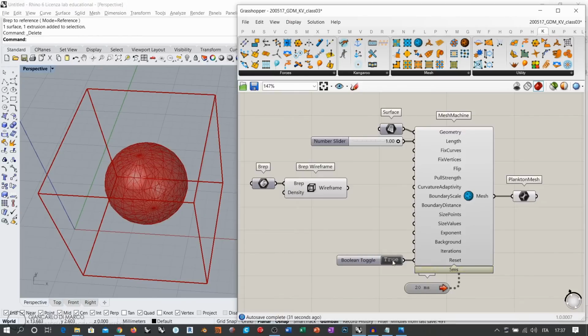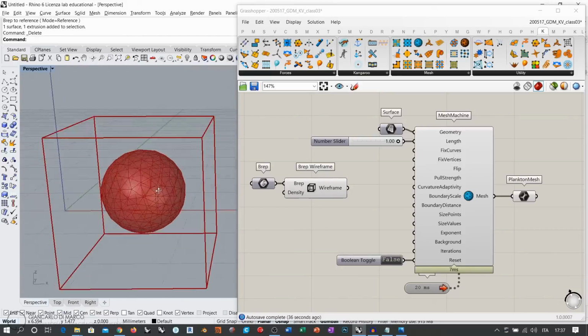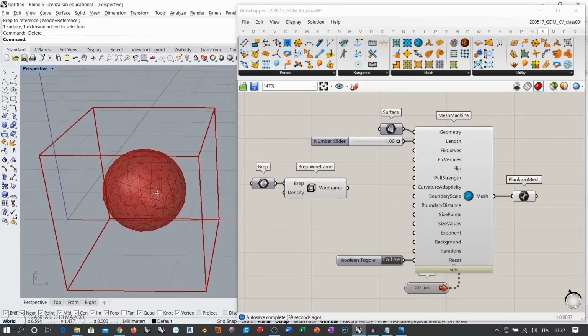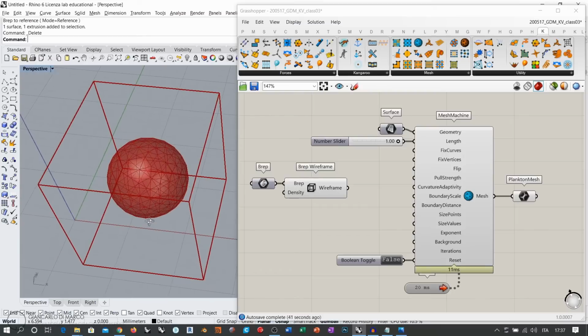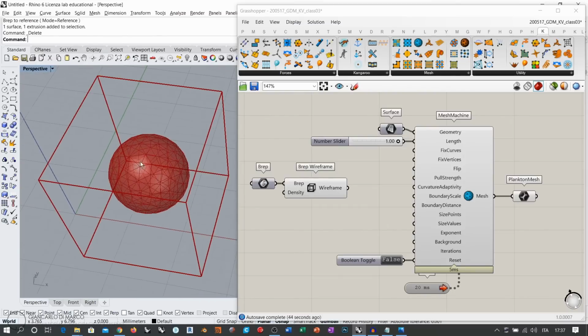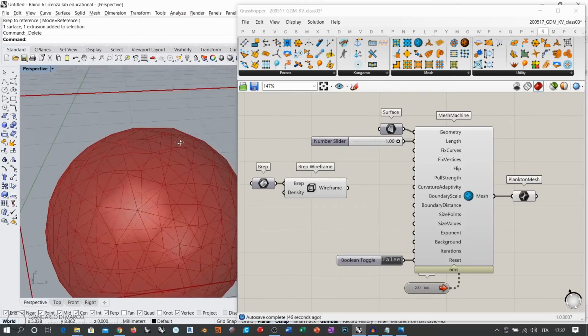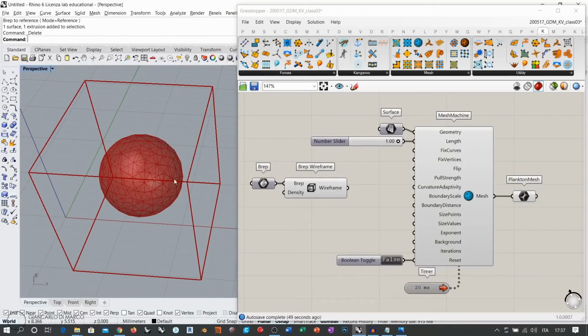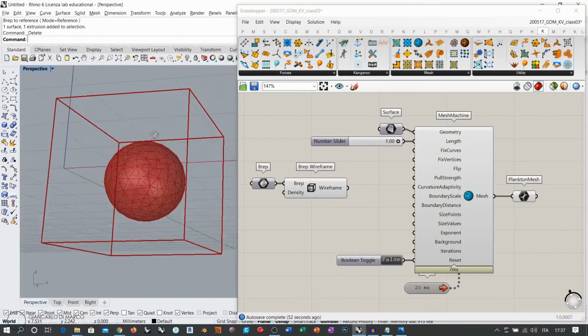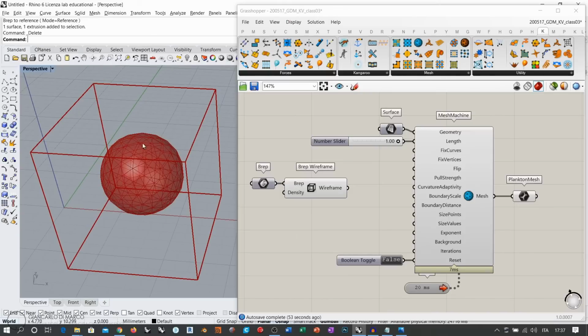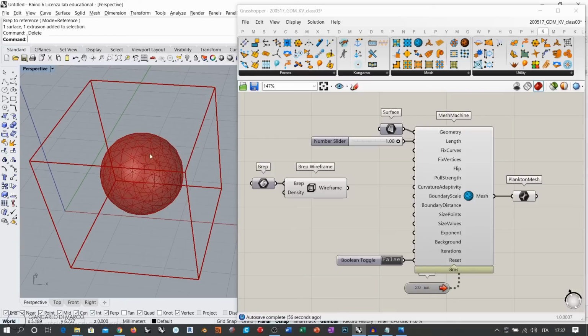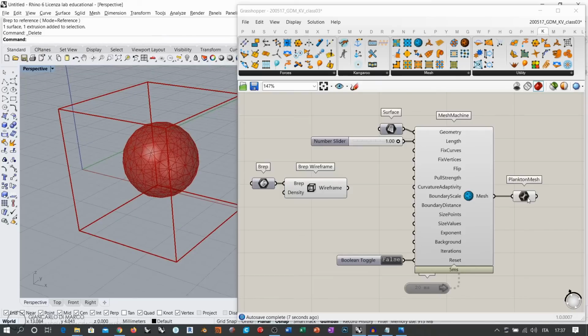We will have some weird behavior in these areas. Okay, but let's run this, and you will see that the remesh is capable of basically converting this into something like, seems like a geodesic dome. It's not perfectly like that because you see that triangles are somehow distorted from now and then. But you see that we have eliminated also the problem at the poles. Once you see that the result is mostly stable, then you can simply stop the timer. So this is no longer outputting actualization for the plankton mesh, and here you have your plankton mesh.